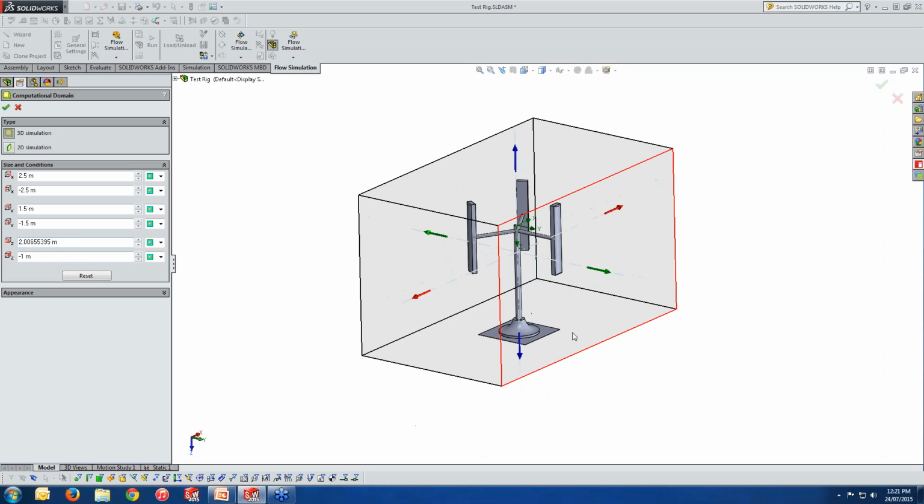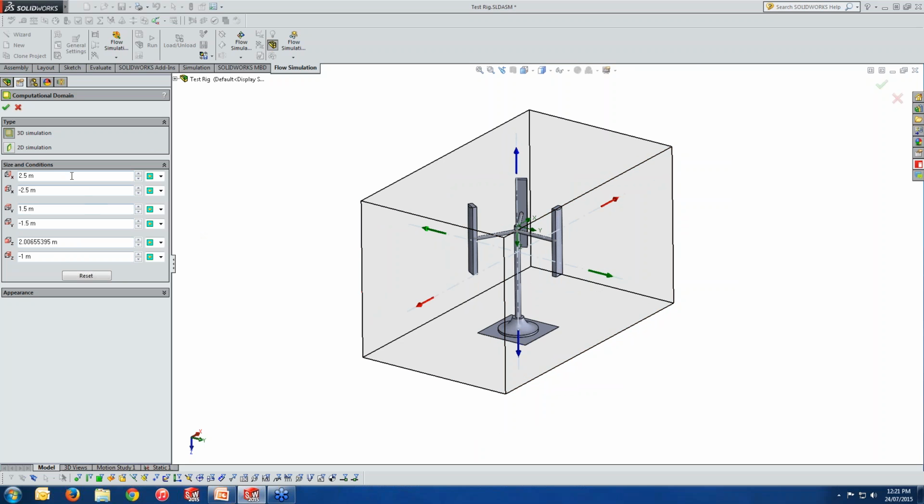One other good thing you can do in this case, if any of the XYZ directions apply, you can say there is a symmetry, meaning exactly the same model is repeating in the X plus direction. That is very good since you might use a symmetry in your simulation and you would like to reduce the calculation time.